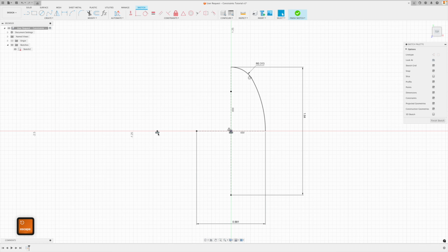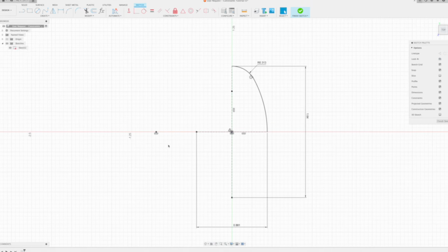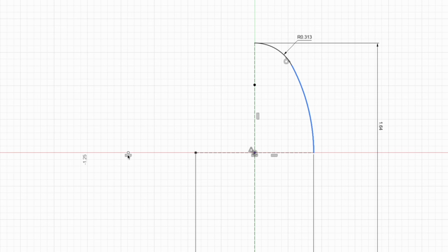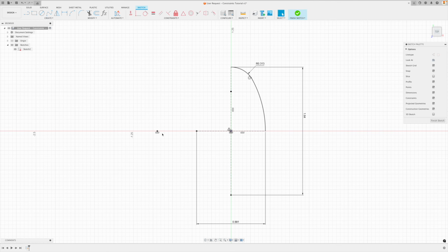And you can see now we've got a horizontal constraint underneath our point. And it also, as I hover over it, look at the origin. The corresponding horizontal constraint matches up. So this is saying that those 2 points are perfectly horizontal from one another. As I do so, this arc also turns black. It has nowhere to go.